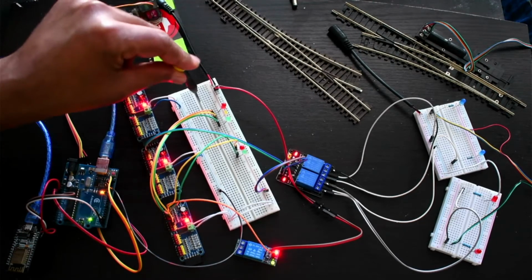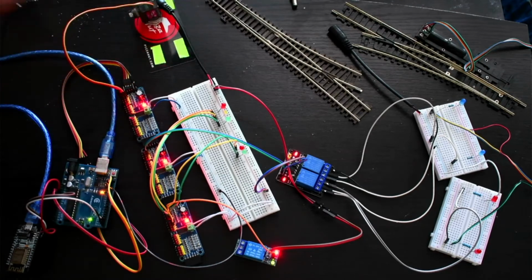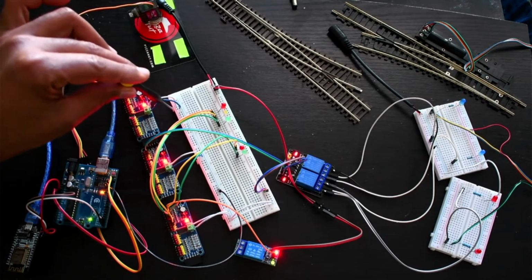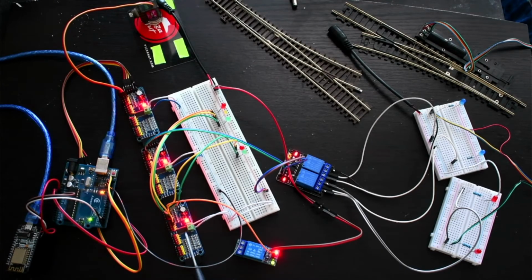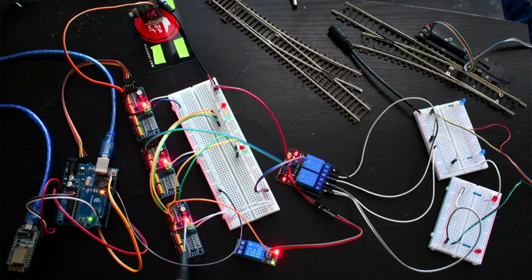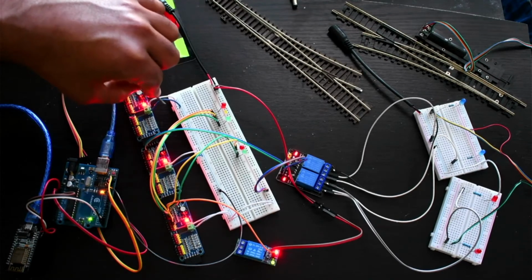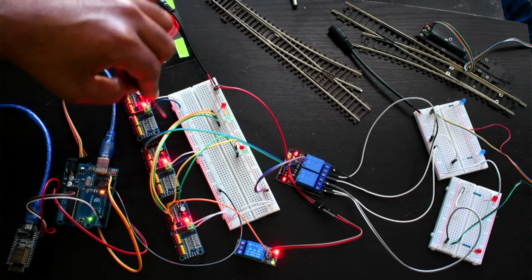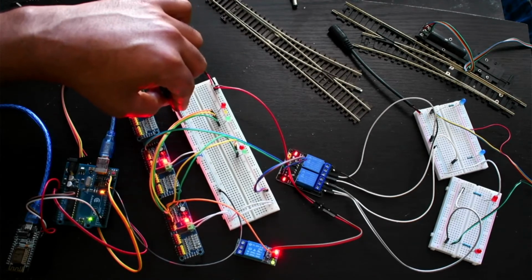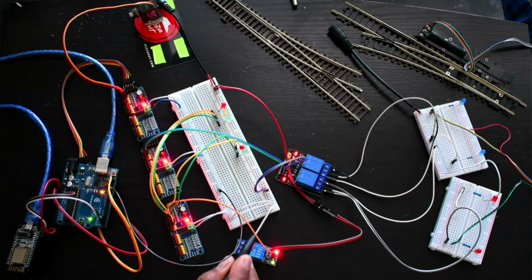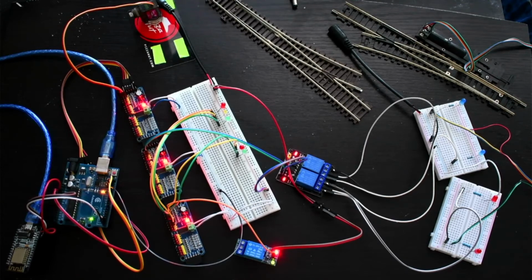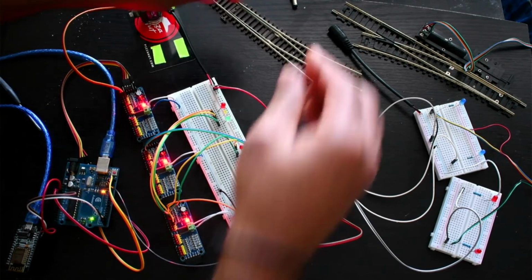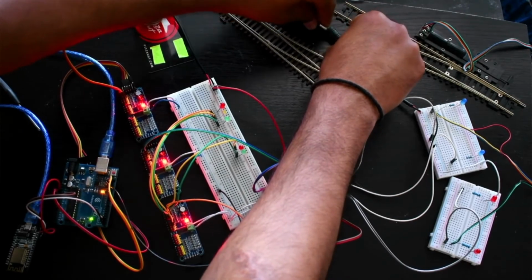Here you can see in this breadboard, this is the external 5-volt power supply coming from an external adapter. For every PCA9685 board we need 5 volts as well as GND. This blue one is GND and this white one is the 5-volt power supply. All the boards take power from this breadboard, and this plus and minus is coming from the other side of the board. So first, let me connect this external 12-volt power supply also.